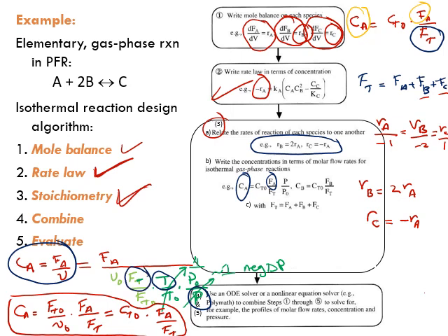Well, T might be variable, not necessarily, of course. If the stoichiometry is all 1-to-1, the delta is 0, the total stoichiometric number is 0, then Ft will remain the same. So Ft will equal Ft naught. However, if Ft is changing because the stoichiometric numbers are different for the different species, or the total stoichiometric number is not 0, then Ft changes. Therefore, I need to provide an equation for Ft.